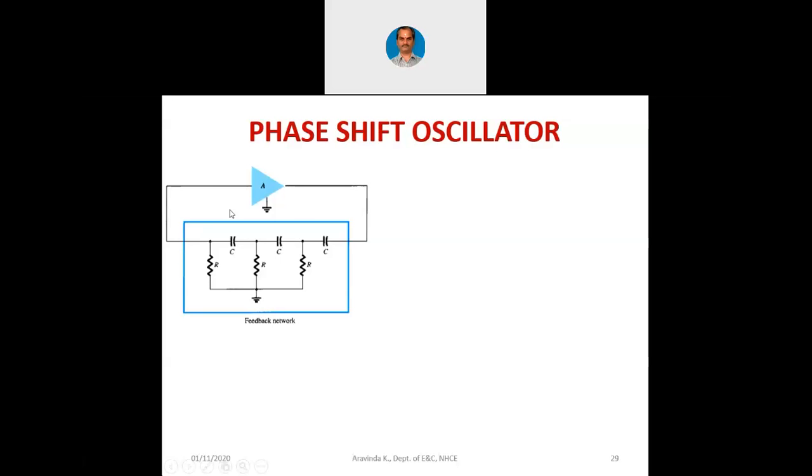Right now, when we are dealing with an ideal amplifier, we can connect a CR also, we can connect an RC also. Ultimately, all 3 are going to produce together 180 degrees. Whether it is a leading circuit or a lagging circuit, it does not matter in our case. But we prefer this CR only. The reason I am going to tell you later on, because we are not dealing with ideal amplifiers, we are going to deal with practical amplifiers.